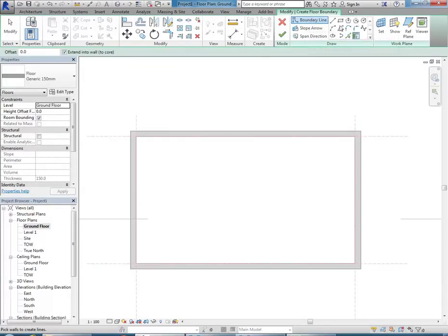And so then you'll see in the ribbon in the draw panel that you have this section with all the different shapes you can draw. Just make sure it's on pick walls, which should be the last button. And just to get used to it, this isn't essential, but it's going to help later if you turn off this option, extend into wall core, on the options bar there. So just those two settings. You've got to be on pick walls for that to come up.